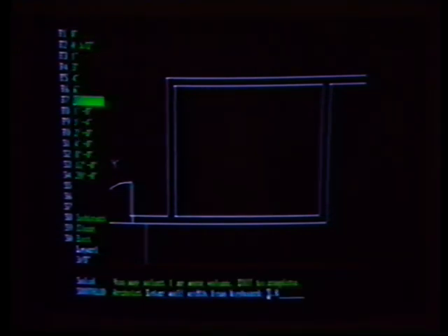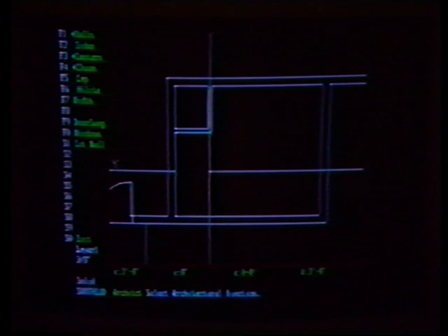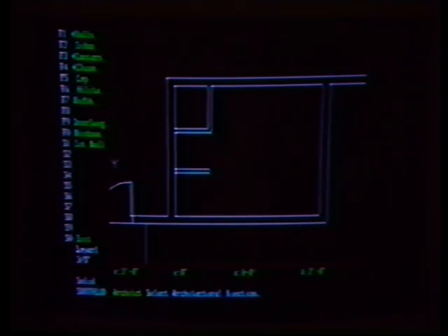These are the walls for the study, but now let's go back and change the wall width to 4 inches instead of 8 inches, which is what we had before, and put in some closets. I'll locate the 2 walls of the closets like this. Notice that they also clean out to the existing walls.